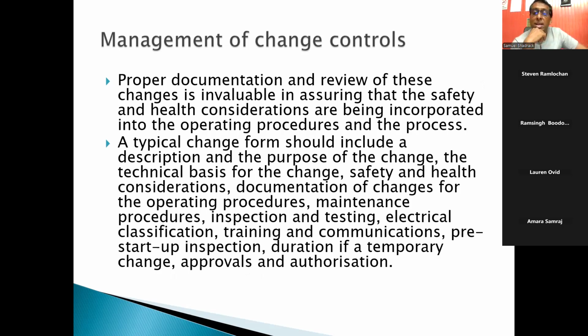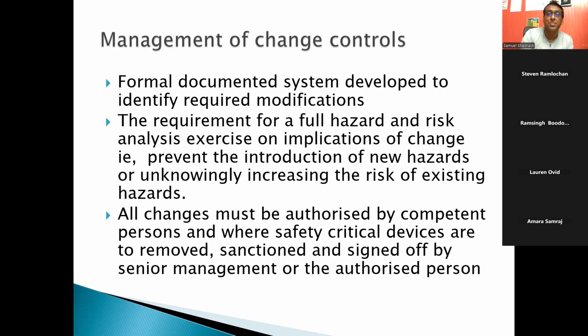And I have a lot more here: safety and health considerations, documentation of changes for the operating procedures, maintenance procedures of what you're going to change, inspection and testing of what you're going to change, electrical classification, training and communication, pre-startup inspection, duration if a temporary change, approval and authorization, and a formal documented system developed to identify required modification. So let me stop, because all I'm trying to tell you is whatever you're changing, you need to document it.